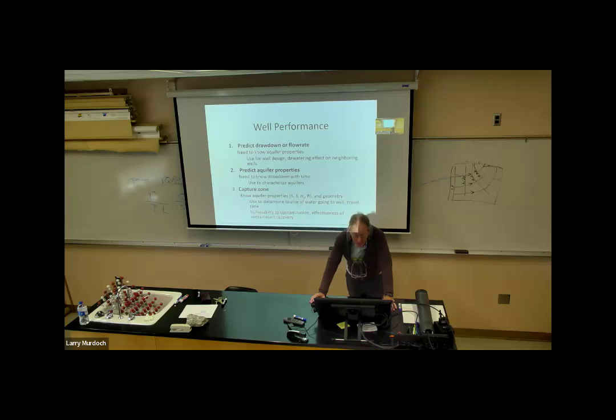This is the procedure for calculating the transmissivity, hydraulic conductivity, and storativity of aquifers. We're going to pump the well. We're going to cause drawdown. We're going to measure the drawdown, and then we're going to analyze that drawdown. Okay, so these two are hydraulic aspects. They're related to the flow and the drawdown.